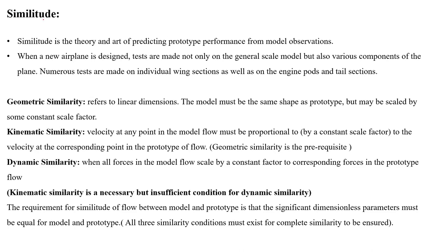Today we will talk about similitude, which we can also call similarity. It is a theory and art of predicting prototype performance from a model observation. I hope all of you know the difference between the model and the prototype.